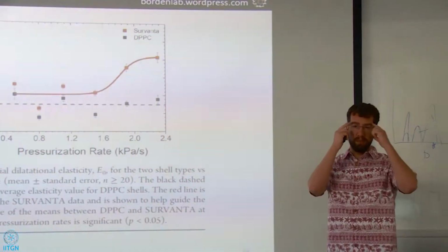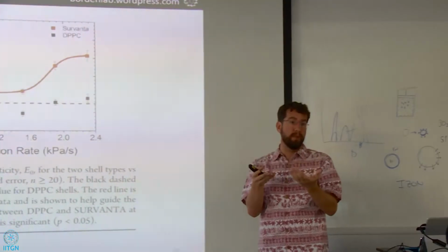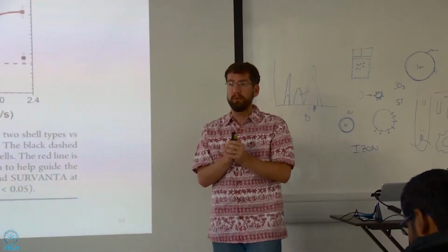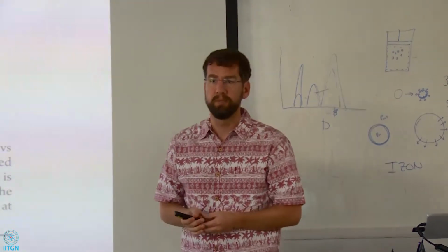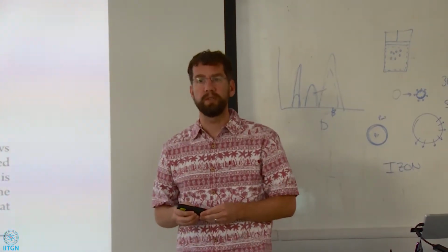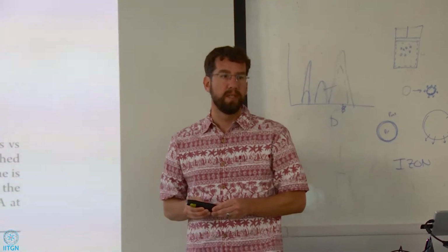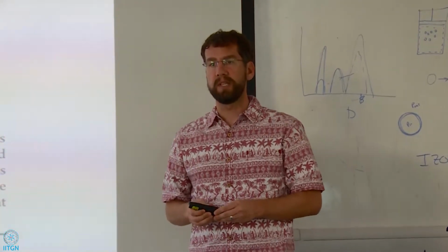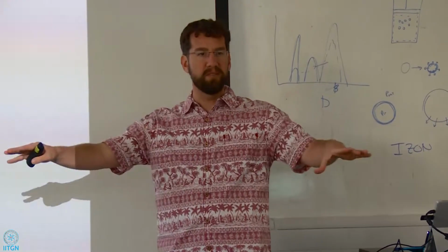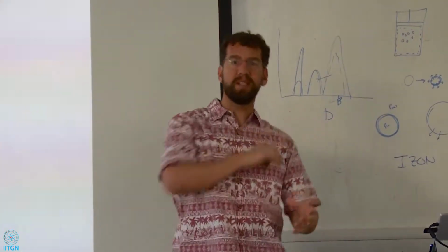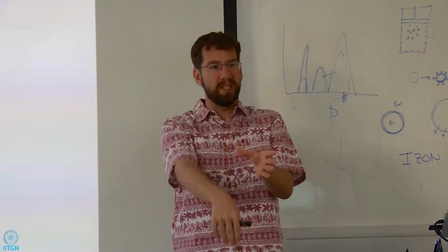But it's just something to keep in mind that maybe the elasticity is a function of the strain rate. Okay? We know about materials that do this. We call them shear hardening materials or shear stiffening materials, right? Like starch in water is one of those examples. If you make a bath of the starch water, you can run across it, but if you stand still in the middle, you'll sink in, right?